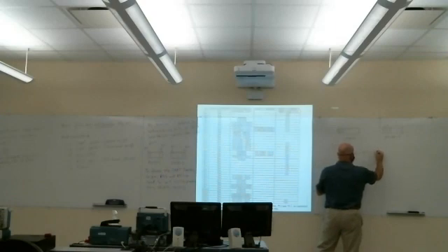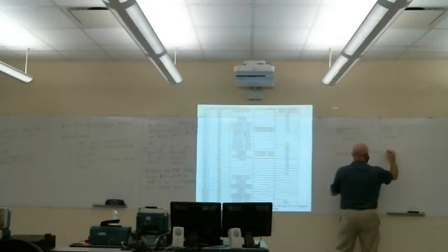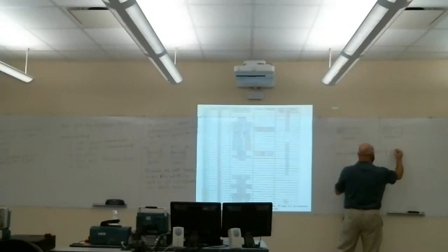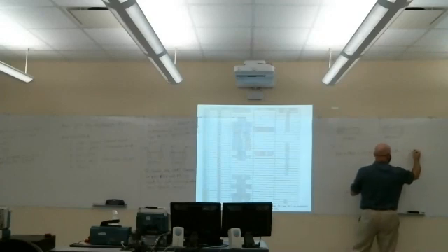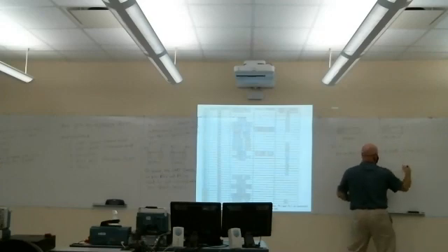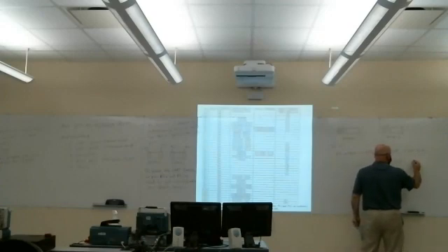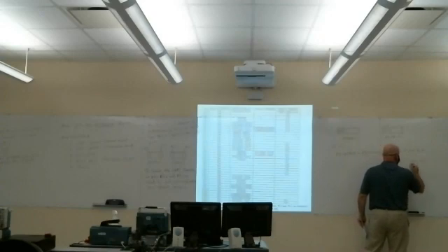But what we want to actually set, what we can do is AND with 0x3F, right? Clear B6 and B7. Because 0x3F in binary would be 0, 0, 1, 1, 1, 1, 1, 1.